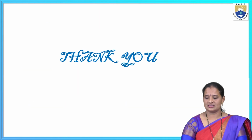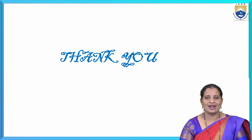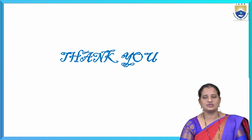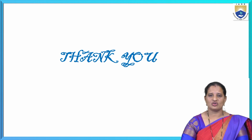I hope it is clear to you all. By using this carry look ahead adder, we can implement fast parallel adders such that the propagation delay is reduced, but the complexity of the circuit is more and it is costlier also. So it is mainly used for applications where fast computation is required. So that's all for this lecture.